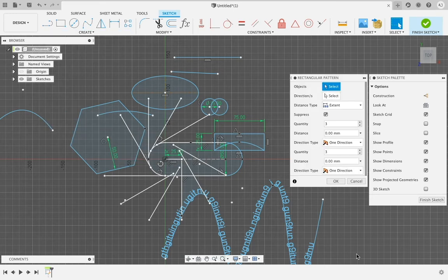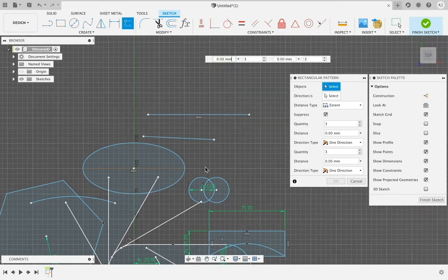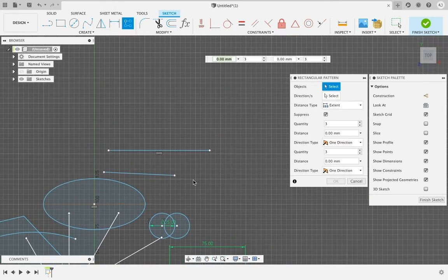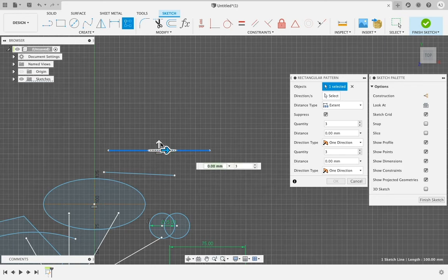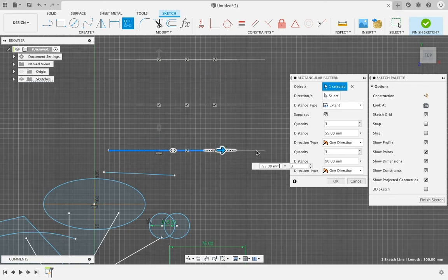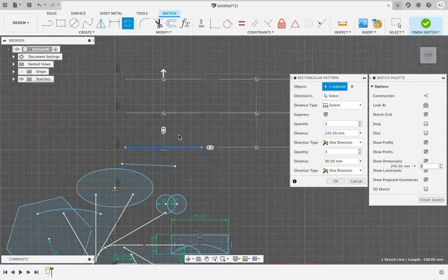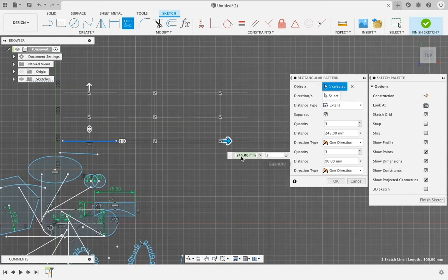Next is our rectangular pattern. The rectangular pattern works like the circular pattern, taking an object and multiplying it over, but allows us to create it in an upwards or sideways direction, creating a whole grid of it. We can specify how high we actually want it off using the extent. We can specify a direction of which it can go, being up or to the right.